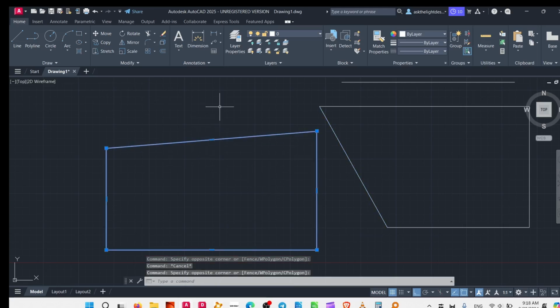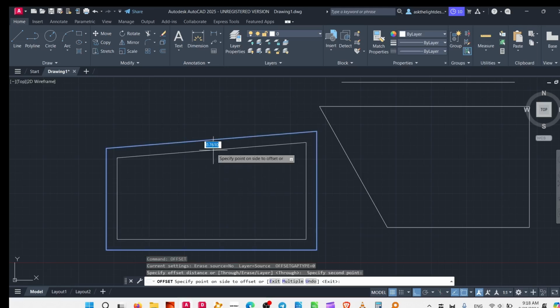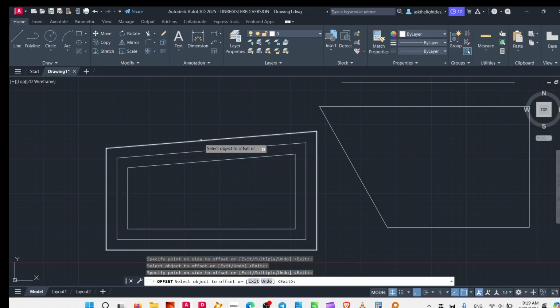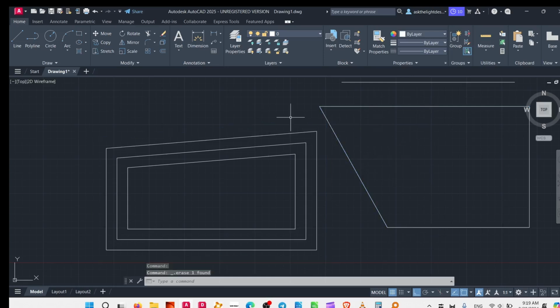Polylines are very good, for example, for making similar objects, and it will all be in the same fashion. It will follow the object philosophy, which does not happen with a line. But at the same time, polylines are sometimes difficult to work around with, whereas lines are very easily modifiable. So these are certain different things.